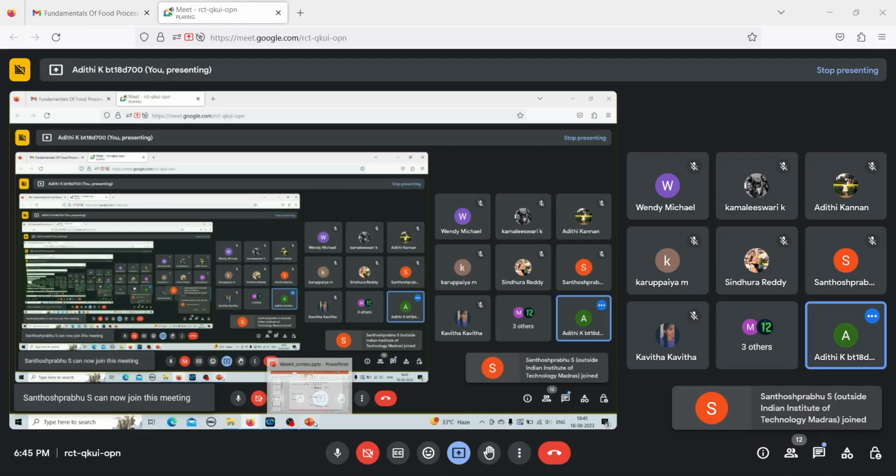We need to calculate what is T1 and T2. So from delta T1 and delta T2, we can calculate T1 and T2. From this equation, delta T1 is 13.52, Ts is 375 Kelvin. From there, we can calculate T1 to be 361.48 Kelvin. And now that we know T1, we can calculate T2. Delta T2 is given as 18.987 Kelvin. T1 we calculated to be 361.48. So 361.48 minus 18.987 is equal to 342.49 Kelvin. The answer is option D. Is this part clear? Any doubt in the equations?